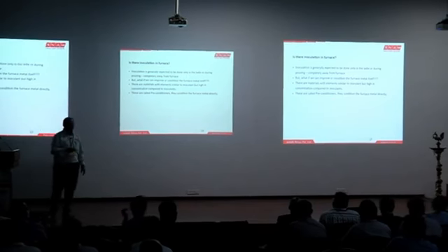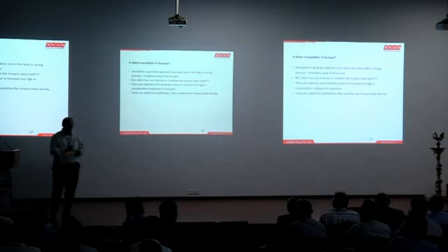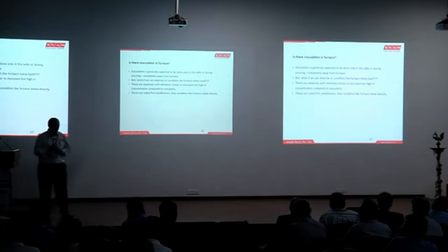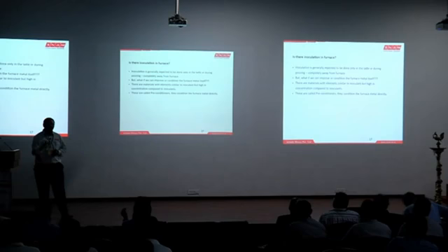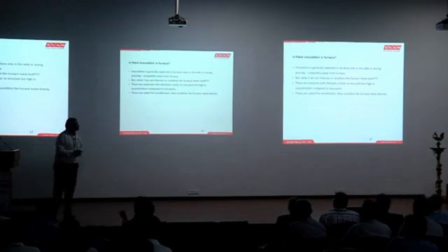So there are materials called preconditioners. That means they will condition your liquid metal. It is like, say for example, Monday, Tuesday, Wednesday, Thursday, Friday, on all 6 days, the first heat will always be different. So the first heat, the second heat, the third heat, though the chemical composition is the same, with respect to time, temperature, holding time in the furnace, and melting rate, the potency of the material can vary slightly. And people who have a holding furnace, there is a tendency that metal from different furnaces can get mixed up, and metal with different potencies gets mixed up. In those cases, to balance the variations, we can do inoculation at the furnace itself. It is called conditioning your material, generally termed as preconditioners.